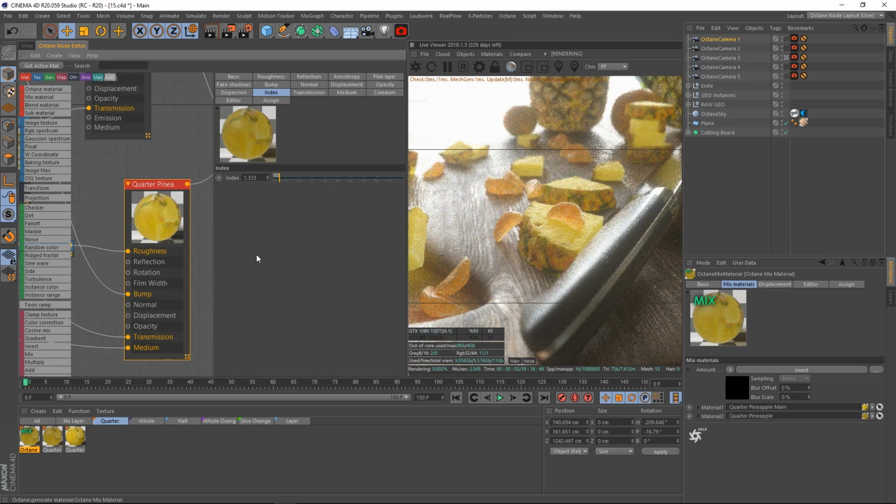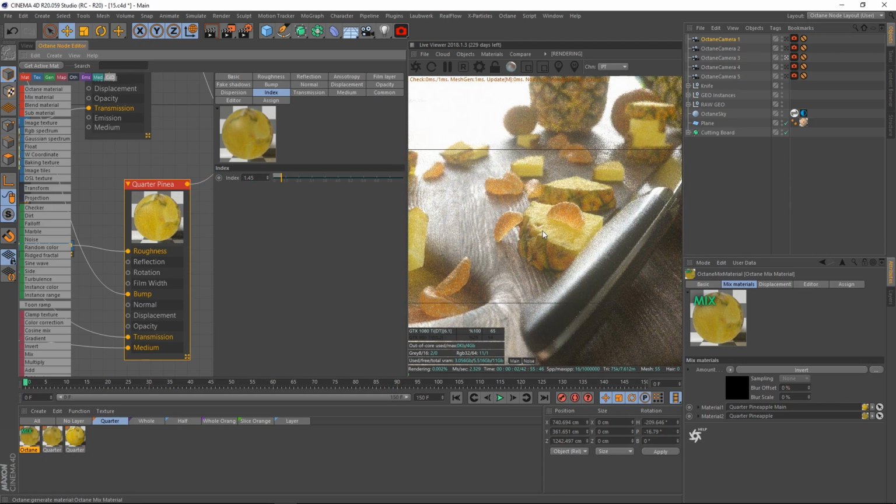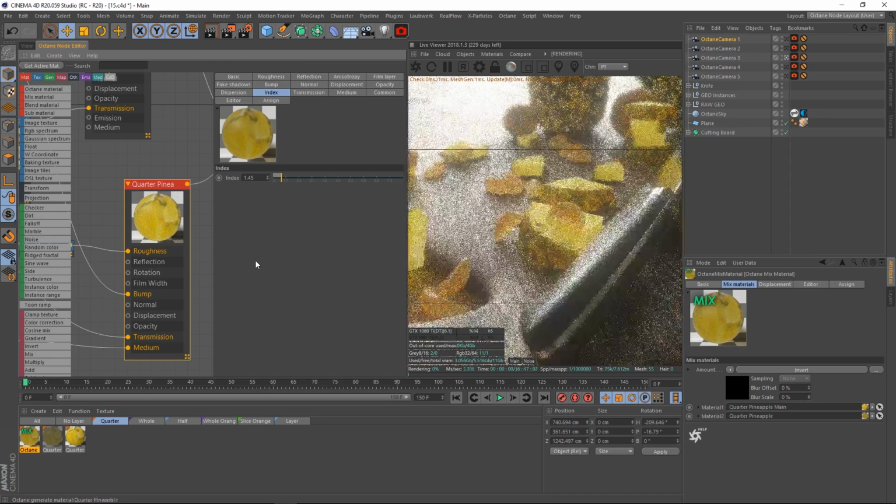Or I could have done a glass at 1.56. I might have just wanted it more reflective, so I might have just done 1.45 just to force those reflections up. That's probably what I did, to be honest, because 1.45 is a pretty safe bet. But either way, more realistic would have been 1.33, because that is the index of water, and that's what we'd be seeing on this pineapple in reflections. So that is this beautiful level of highlights we're getting off the surface. That said, 1.45 did add a little bit more pop.